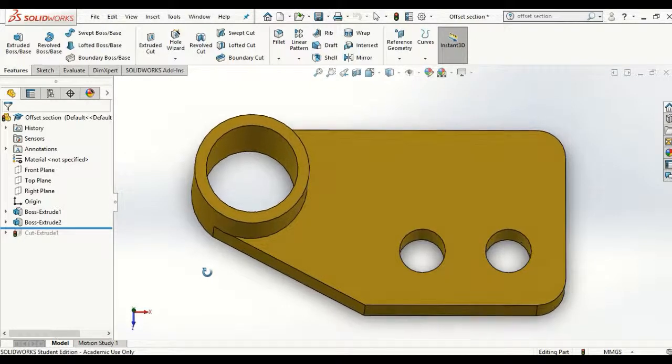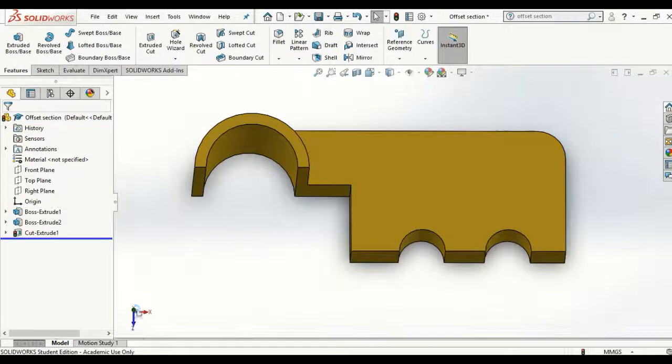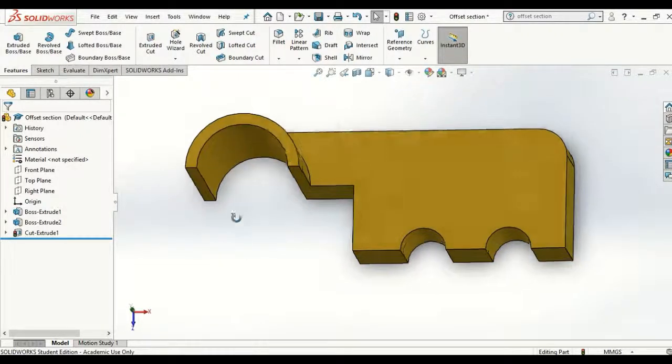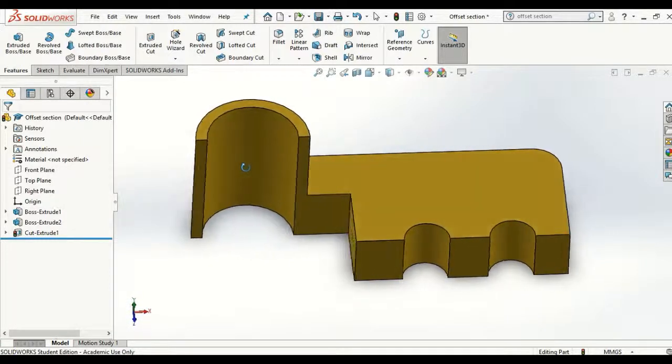So here in this example, we can see when it is subject to the cut, our cutting plane starts from the left hand side. It cuts through the large housing for the flag stick itself. It is then offset at a right angle, and then it is offset once more until it cuts through the entire piece. So we can say that it has exposed all the features of this piece, even though they're not in a straight line. So we can see the surfaces that have been exposed. And that wouldn't have been possible if we were just to have used a normal or a straight cutting plane.